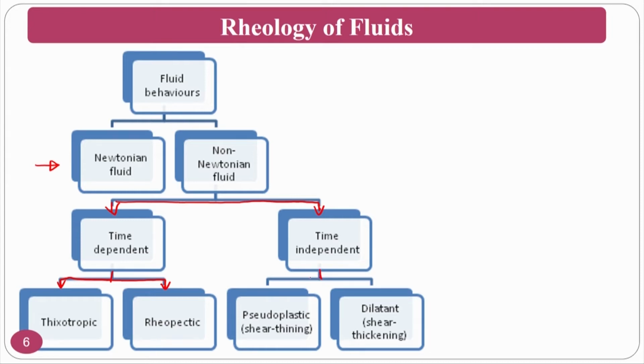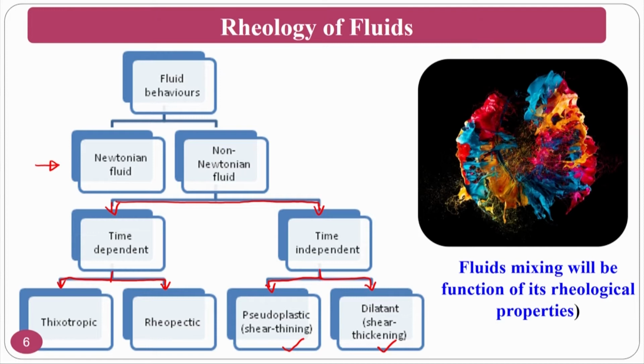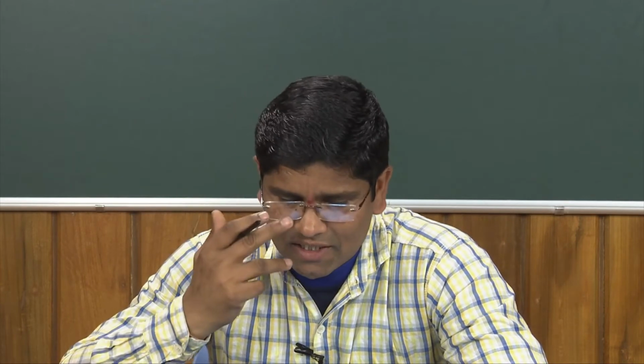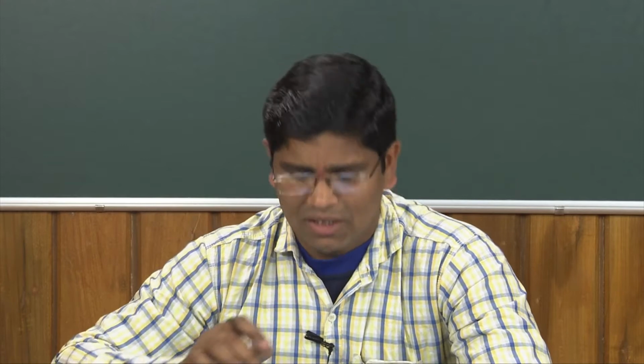In the time independent, again it will divide into two things, one is pseudoplastic as well as dilatant. Normally we study mostly about the time independent one, that is called shear thinning fluids, shear thickening fluids and all those things in the upcoming slides. So the rheology particularly about these cutting fluids helps in proper mixing as well as proper flow and deformation whenever the intricate complex regions of chip tool interface or workpiece flank surfaces comes into picture. So this is the beauty about the rheology.